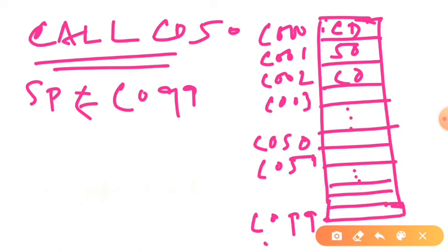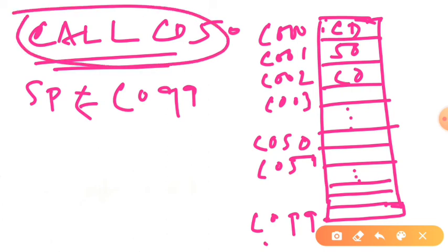Now what will the microprocessor perform once it fetches this call instruction from the memory? It fetches the higher order byte from the memory address C002, then it stores this memory address where the execution should be transferred, the C050 memory address, temporarily inside the WZ register pair.